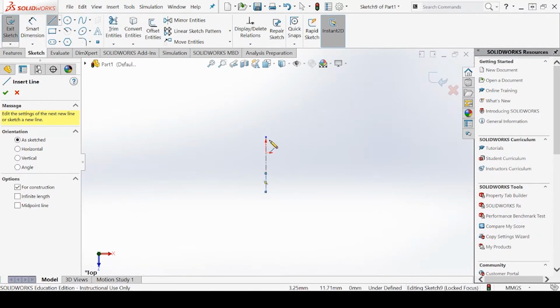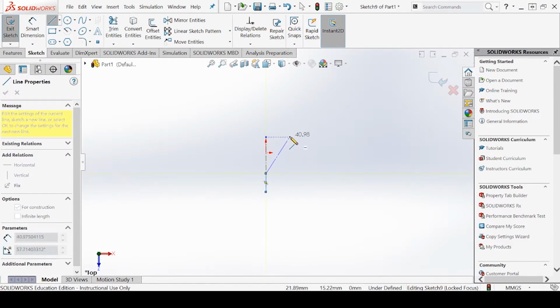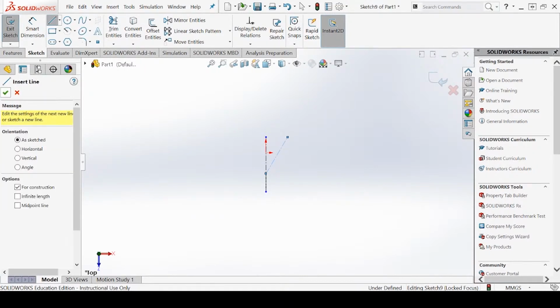Again, using geometry, this time on the top surface, knowing that this radius is 20 millimeters and that this new distance where it's going to intersect this line is 34.64 millimeters, I know that this line, which is going to be at 30 degrees, the maximum acceptance angle, is going to be 40 millimeters long. And then I can go down and change this to 60. I know that the acceptance angle is 30, but SOLIDWORKS measures from this x-axis here. So from here up, it's going to be 60 degrees. However, the acceptance angle is measured from this center optical axis, so that's going to be an angle of 30 degrees. So we're right on point with that.